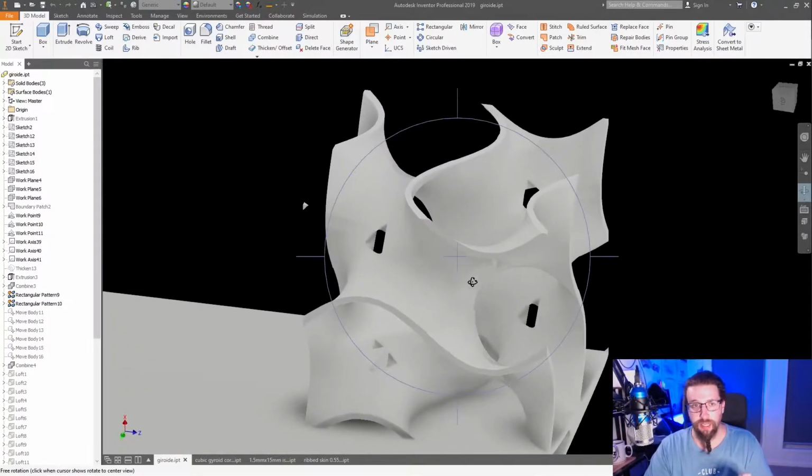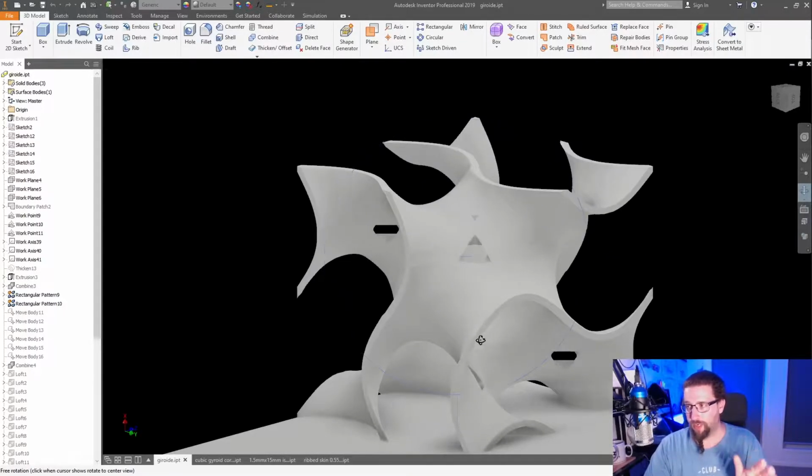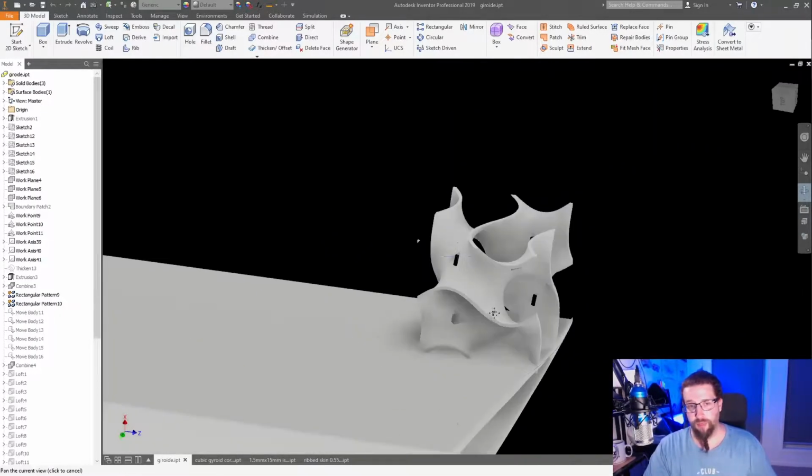It looks like cheese. These holes are also intersecting points of the surface that when you tessellate the geometry, when you convert it from a surface to a quad or tri-geometry, there are errors induced through the math in these areas, and when you go to do Boolean operations, the stuff going on in these points doesn't Boolean. The math is like divide by zero stuff, trying to put a hole through a Mobius strip surface. The math just doesn't want to deal with it, so those are the errors that we've been seeing.